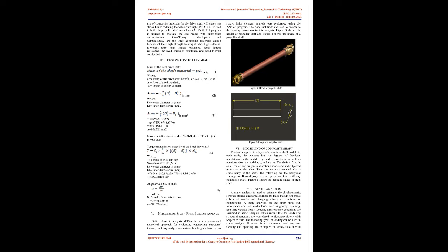imported into Ansys software for FEA analysis. The propeller shaft design will next be revised and analyzed under the same material and boundary circumstances. This improved shaft will now be analyzed using composite materials under the same boundary conditions. In order to discover the ideal bonding angles, the layer wrapping angle between the layers will also be adjusted. In order to reduce the time required to pick the composite material and layer wrapping methods, a genetic algorithm will be used in this study. The findings will be compiled and compared in order to choose the best sample.